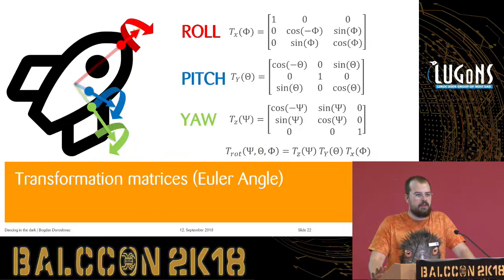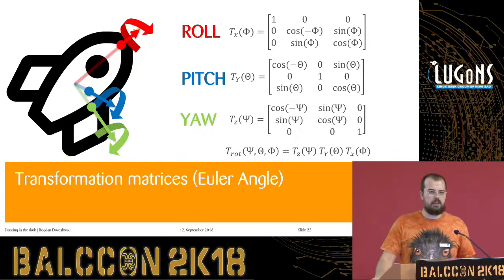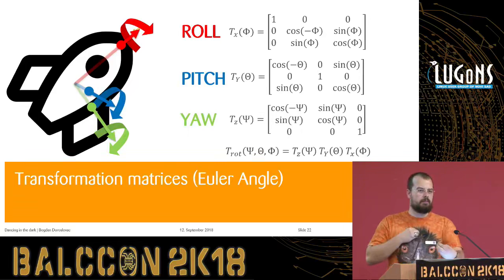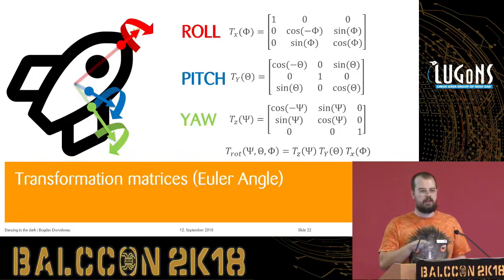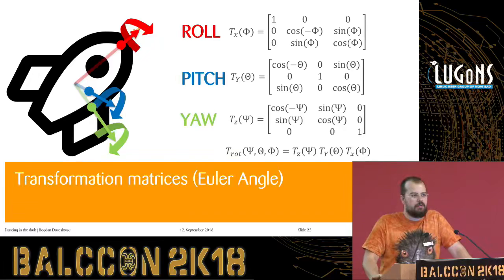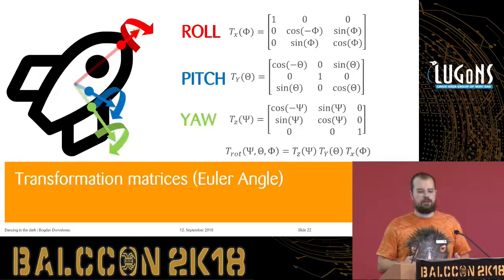And typically Euler angles, as they are called, are named alpha, beta, and gamma. But much more widely used, and the thing that I'm citing here, are roll, pitch, and yaw, which are basically the 3 properties of the body navigating. The roll is the rotation about its dominant axis, so typically the axis of symmetry, let's say, of a missile. The pitch will be its tendency to go up and down, and the yaw will be its tendency to go left and right. You'll notice that in missiles it is decoupled, while in aircraft it's highly coupled. It's typically roll and yaw. You cannot that easily shift that system.